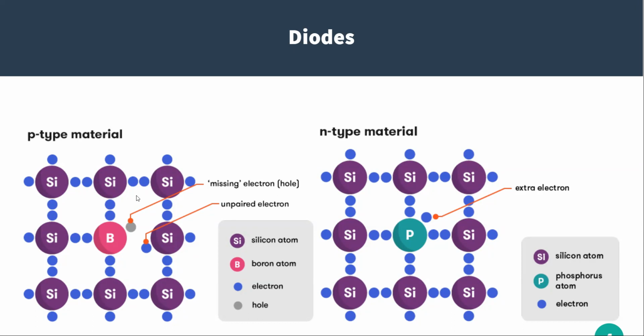And getting across that energy gap has to do with why it's 0.3 or 0.7 volts and all the physics stuff, but you just need to know N and P-type material makes the junction. And we do transistors the same way, except we use 3 pieces of material. We use an N, a P, and an N, or a P, an N, and a P.